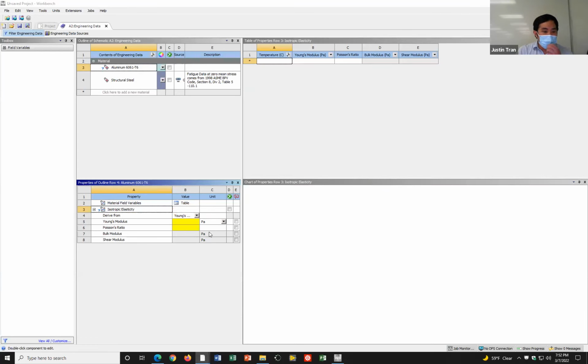All right, so let's start with the Young's modulus. The Young's modulus is given to us in PSI, so let's make sure that we swap the units, okay? You want to input the Young's modulus in different units. You can click on this down arrow right here, okay? And let's change this to PSI because that's the units that we were given the Young's modulus in.